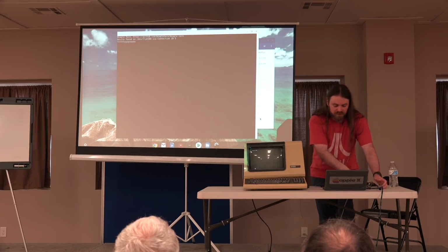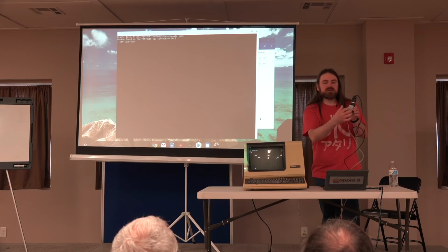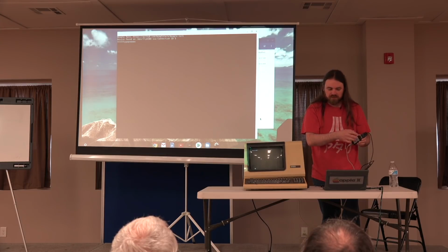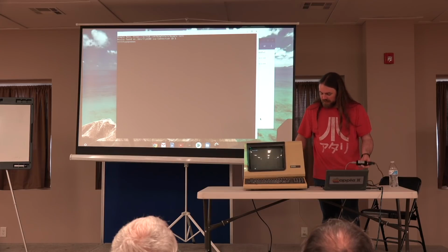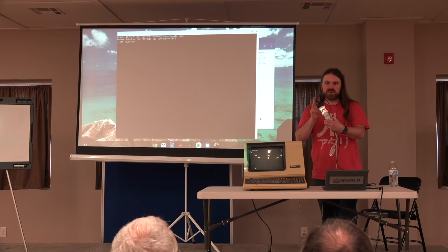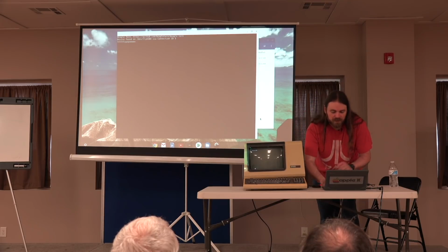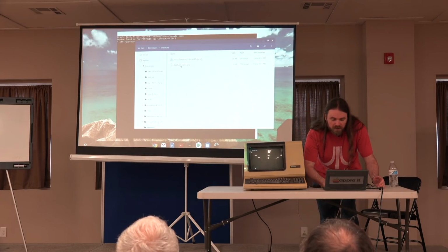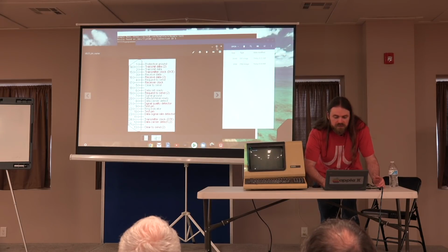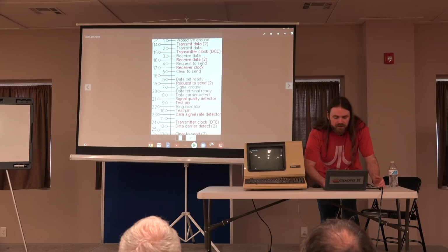But of course, this is a computer, and this interface box is DTE wired. In order to connect these two, I need what's called a modem eliminator or a null modem, which is an adapter that switches the serial wires over. Here's a pinout of the connector on the back of the terminal.